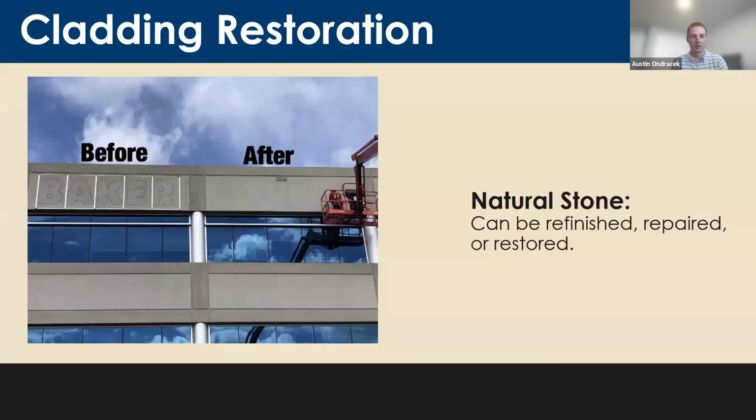Just another close-up of here. This is a limestone on the side of a building. Everything here was refinished on the face of it to take off the lettering and bring back that inherent same color of the stone, to change it. So didn't have to tear it out, didn't have to really do any other work other than just taking off that fine top layer of that stone and keeping it on the existing building.